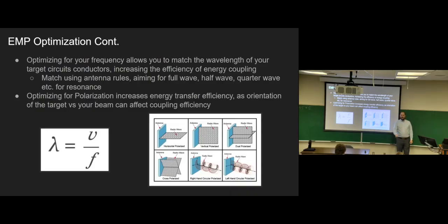If I'm holding my antenna, let's say it's a rod, vertical, and a vertical wave hits it, I receive it perfectly, 100%. If a horizontal wave hits it, I get none of it. Polarization has a massive effect on how energy couples. And it's actually very useful for communication. It means you can use the exact same frequency, and as long as your polarizations are sufficiently different, you can talk and receive at the same time. That's how mobile technology works, among other things.